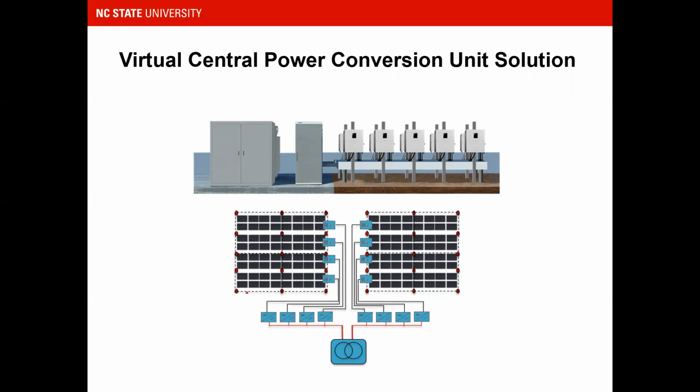Using string inverters, we are improving the reliability compared with the central inverter. We are reducing the cables. If we reduce the cables, we are reducing losses, because the distribution that we are using here is based on DC current and higher DC voltage. Less power is lost if one inverter goes down, less maintenance, less technical expertise required for maintenance and installation.